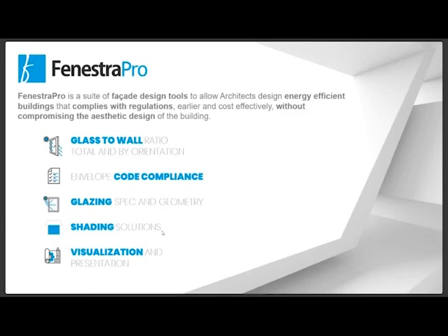We can look at shading solutions within FenestraPro and the effects of those shading, whether it be shading devices or the shading from surrounding buildings and the building itself, on, again, things like daylighting, on things like solar heat gains. And we can visualize and present that data and that feedback graphically and in a manner that we can use to demonstrate your designs to, whether it be clients, other members of the design team, or your own colleagues.